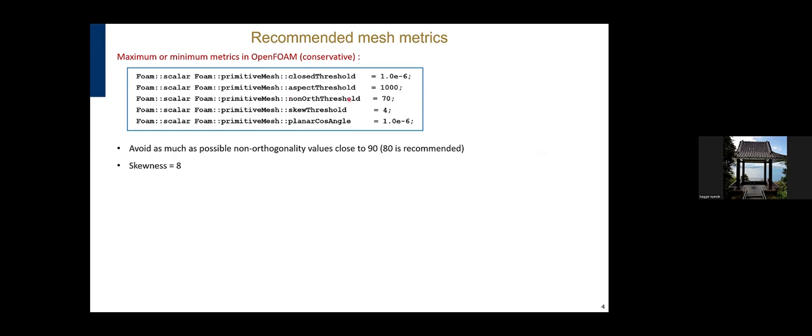Now, for the skewness, typically 4 is what they recommend, but you can have a skewness of up to 8. If you begin to exceed some of these numbers, then you know you have a problem.